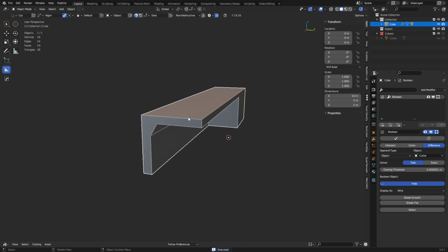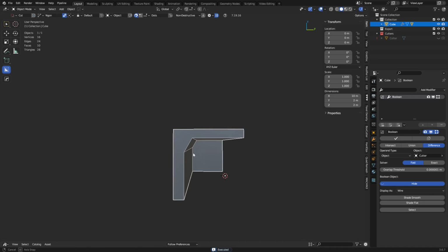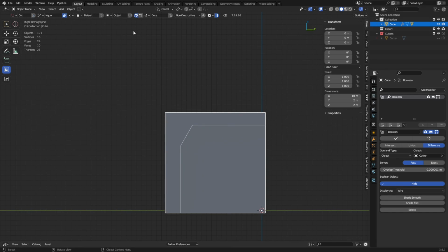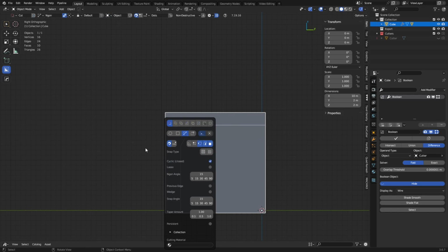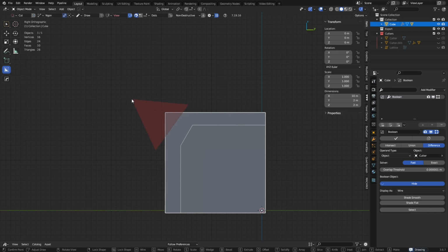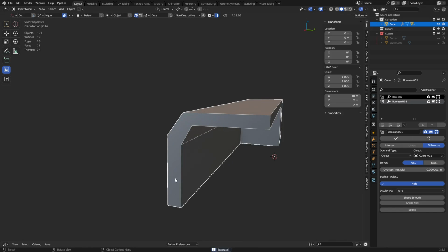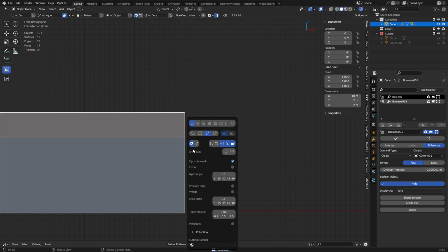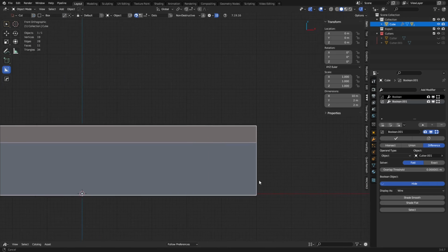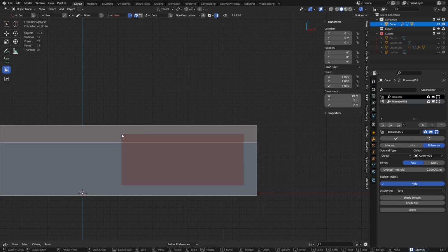That's it. You do this from the orthographic views, holding Alt while orbiting. You could turn on view align and ortho. Use the N-gon cutter, and you can just cut triangles like this to do little chamfers, things like that. You can go to the side, you can use a box cut. Come over here and you could do this.